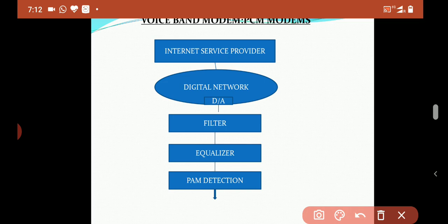It relies on the digital network to carry an unaltered digital signal from a digital source to a digital to analog conversion device at an analog subscriber interface. This codec converts the PCM code word to a PAM sample that is detected by the receiving customer premises modem and converted back to the original PCM data.